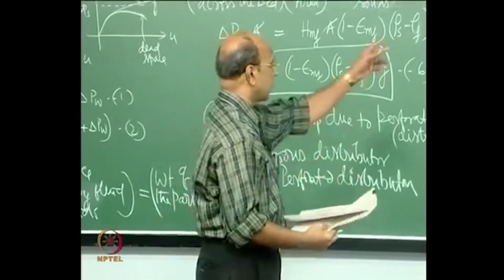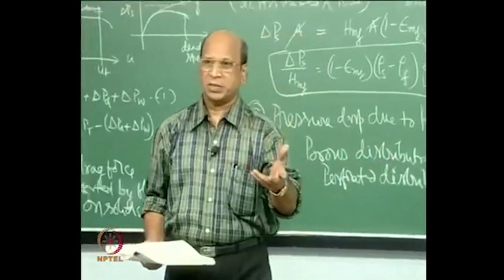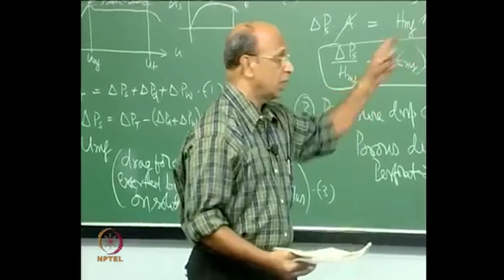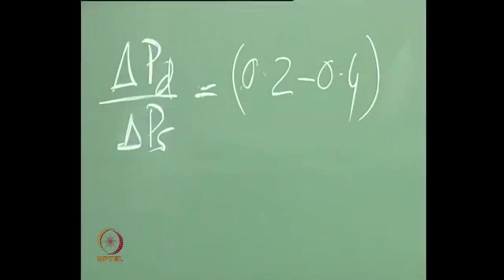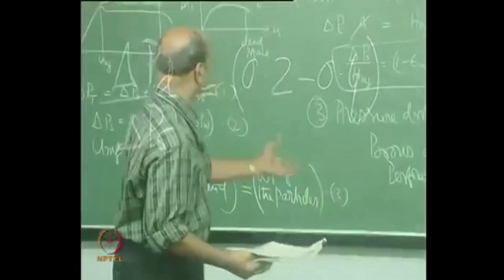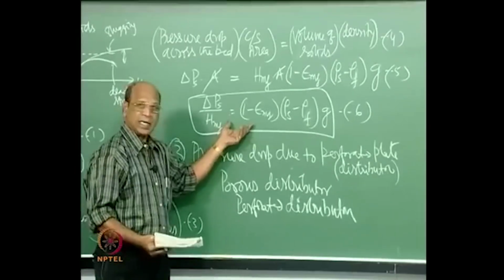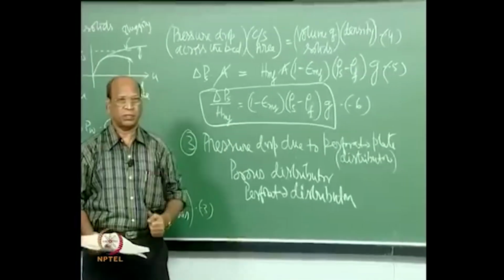So, this thumb rule was observed only by experiments. So, you get good fluidization when you use this kind of values. That means, the pressure drop should be 20% of pressure drop due to solids, which you can estimate from this. You can calculate from this, and I do not know whether you have designed anyway.